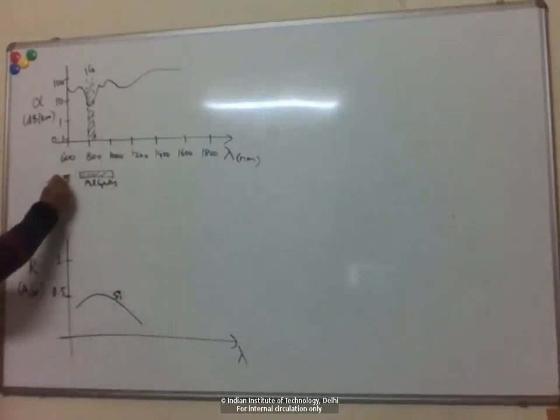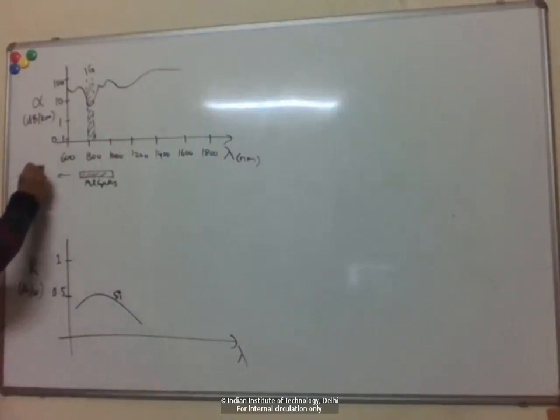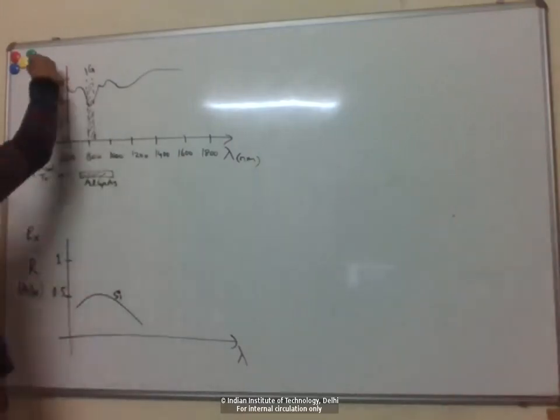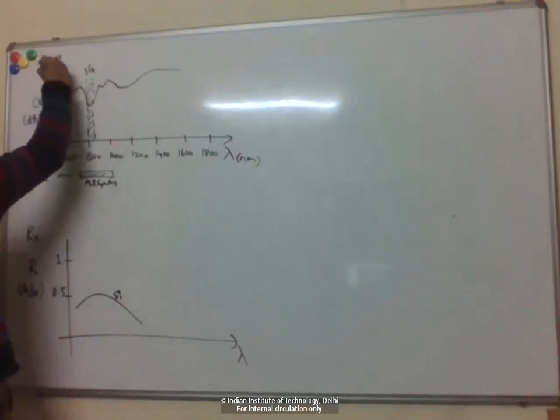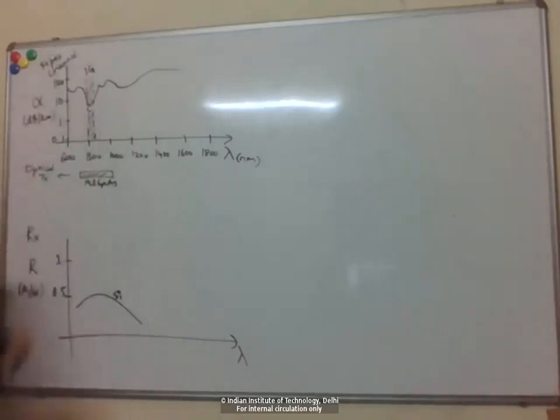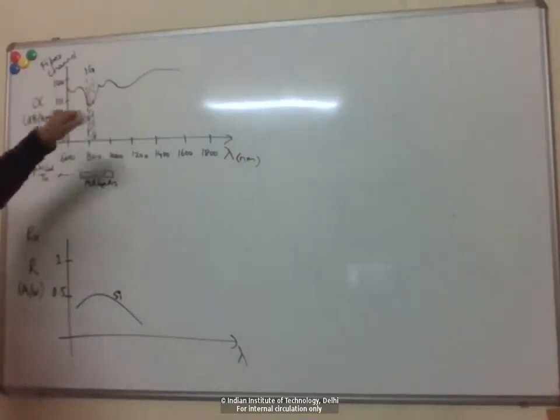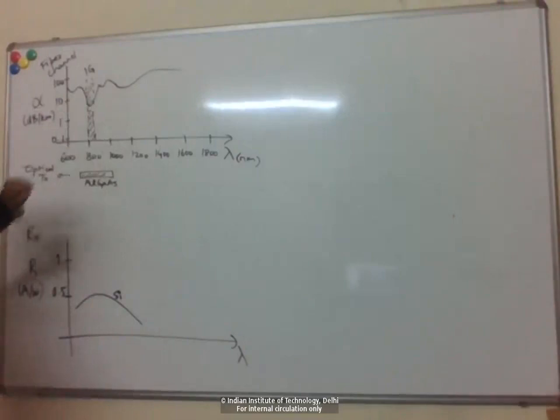So these are sources or transmitters, this is receivers, and this is the fiber channel. That's the first generation of optical networks: sources based on AlGaAs, fibers which had a minimum loss around 850 nanometers, and detectors based on silicon.